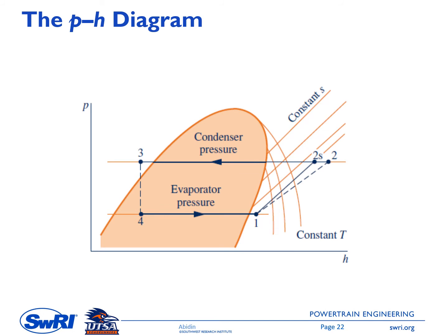And you can see in here the unique thing of the pH diagram for the process connecting state 3 to state 4. This is a throttling process, and the enthalpy stays the same. Therefore, we have a straight vertical line connecting point 3 to point 4. And then other points stay the same. And you can see in here the dome line is a bit inclined to the right.